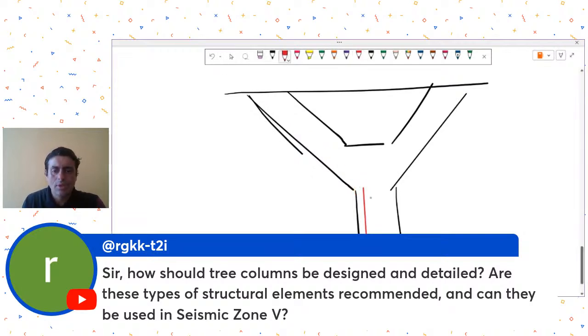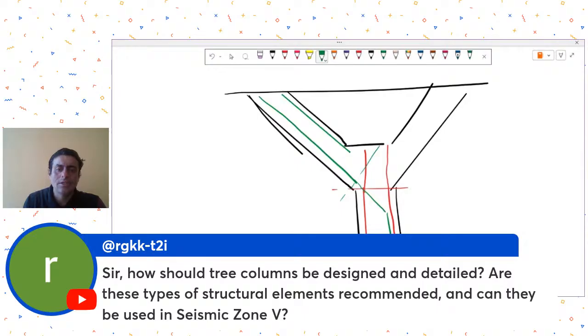Maybe you need to take this bar and beyond this face develop till a distance of LD for this bar. Then similarly, for beyond this face, you need to maybe take it to the farther face. That is what we generally do in joints that are susceptible to opening, like we do in staircases also. So this type of arrangement you may have to make, and for that whatever detailing lengths are required, you need to study well.